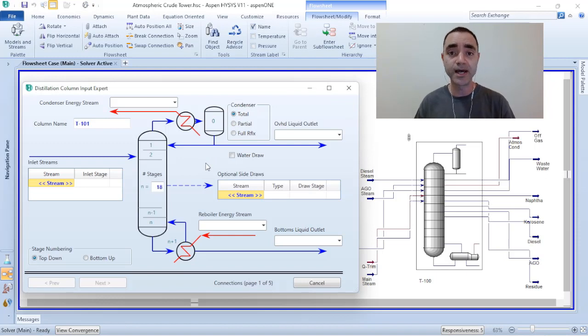And in this way, I don't have the splitting or the equilibrium between vapor and liquid in my condenser, because now I am condensing everything at the top of the distillation column. So now I don't have a stage of equilibrium anymore.